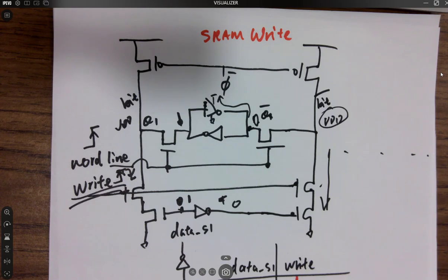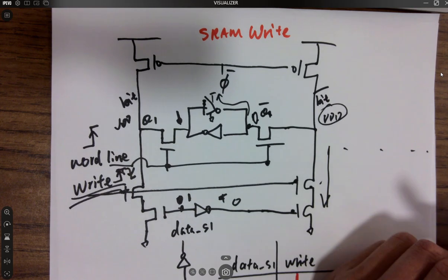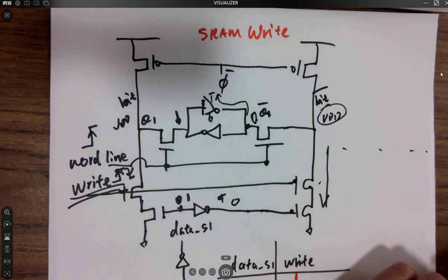So the Arduino Uno chip, $2, so easy to solder, so cheap, just doesn't work for our application. So 2 weeks before the microcontroller class, we switched to the Mega chip, $17 per chip, and super difficult to solder, and we just have to do it. So in that case, you know that the size of the RAM is critical. So we are looking at microcontrollers. If you look at the size of the memory, it will give you different prices, different costs.